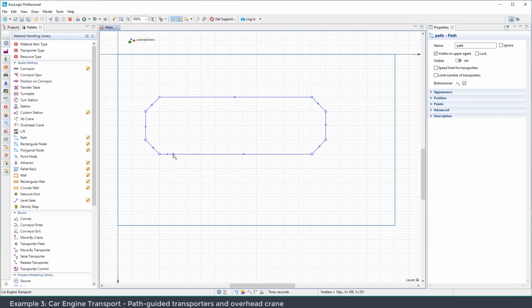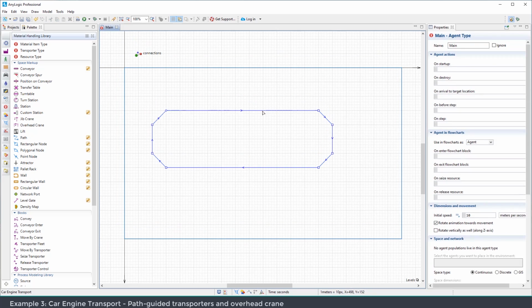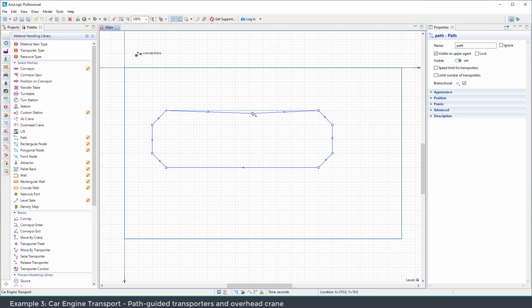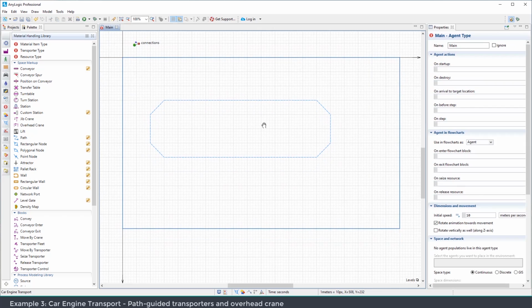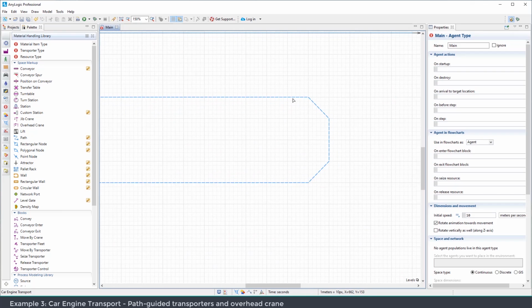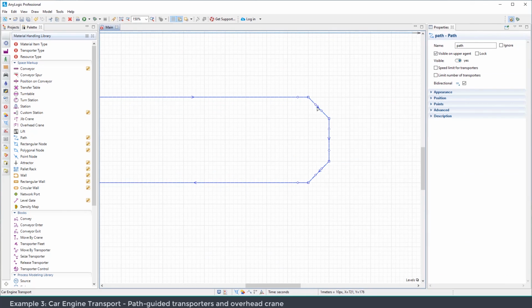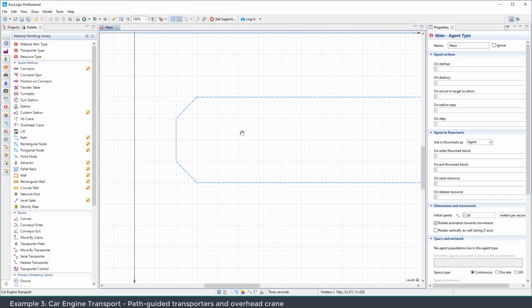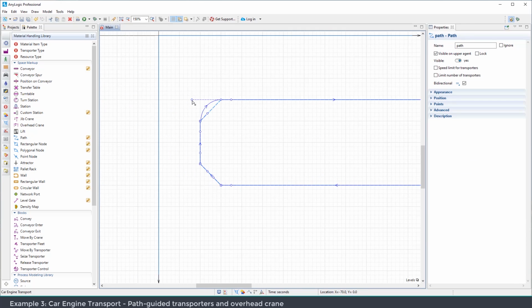Alternatively, AnyLogic lets you draw curved sections while in the drawing mode by holding down the left mouse button as you are placing the path's next turning point. To change the edges to curves, right-click on the path and select Edit using guiding lines. 2 new handles will be added to each path section that lets you add or change the curvature of a section.